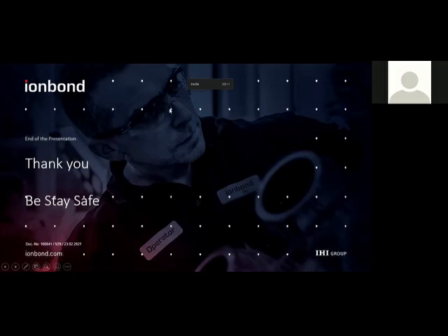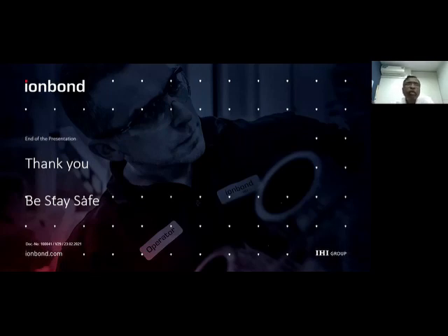So the first question is from Mr. Karthikeyan. Is there any coating for powder metallurgy parts? Powder metallurgy parts are sintered at a low temperature, so we can't use CVD based coatings for powder metallurgical substrates, tools or components. We can use titanium nitride or aluminum titanium nitride PVD coatings for powder metallurgical tools.